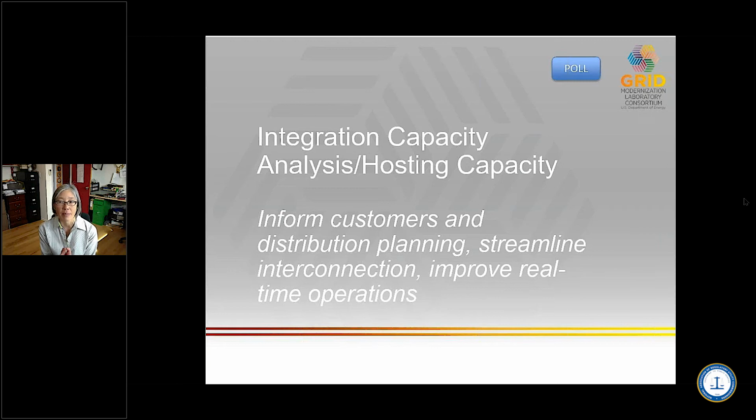So this is an approximation of the potential adverse impacts of DER on the distribution system. And when people talk about hosting capacity, they might say, I've got 1.2 megawatts, or they might say I've got 50% of the peak loading of this feeder, or they might give you a range. At 1.2 megawatts, I know I can handle it. At 1.6 megawatts, I know I can't take anything, and in between, it will depend.